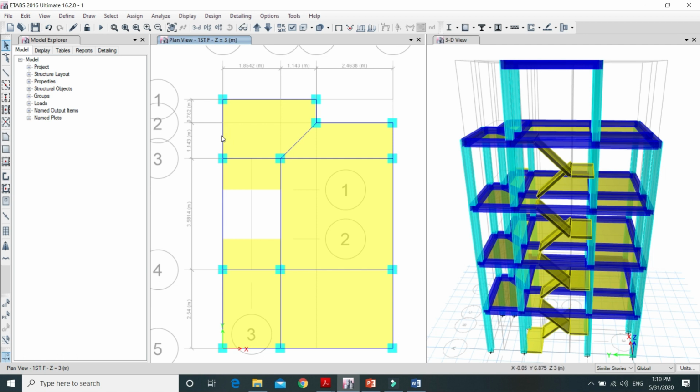For example, if I select this beam and assign a specific load, that is loads due to the walls above it, and if I am working in the all stories platform, and if I specify a certain main wall load, then the load will be assigned to the beam of every story, that is to this beam, to this beam, to this beam and to this beam also. But you can see there are walls above these three beams, but there will not be any walls above this beam, but loads have already been assigned to this beam also.